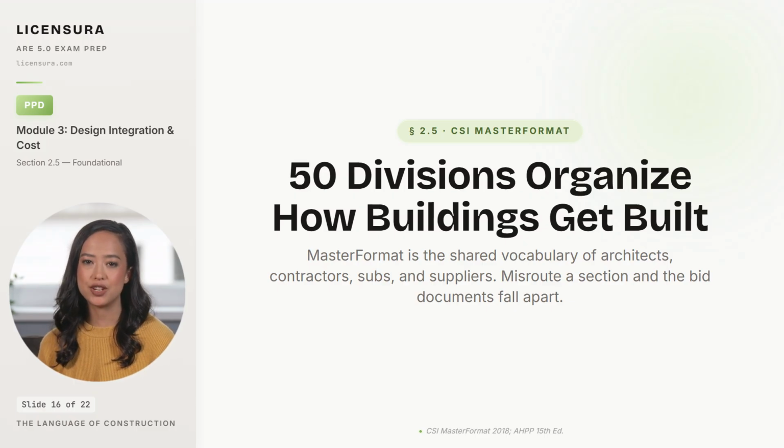You will see exam questions that test whether you know which division covers which work. Concrete is Division 3. Metals is Division 5. Thermal and moisture protection is Division 7. Openings is Division 8. HVAC is Division 23. And you must answer without looking them up. Get the divisions wrong on a real project, and the contractor builds the wrong scope, the owner sues for the missing work, and the architect's E&O insurance pays the gap. Let me walk you through the 5 division groups so the 50 numbers stop feeling random.